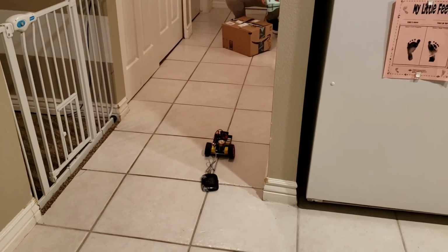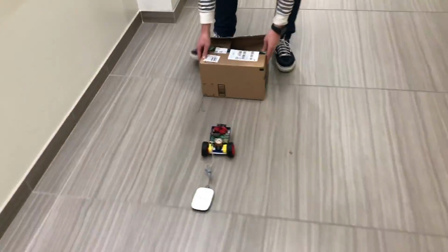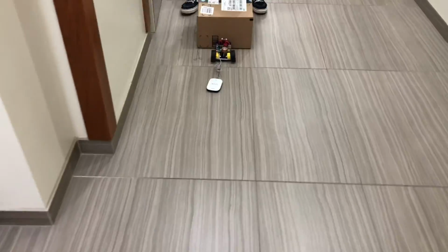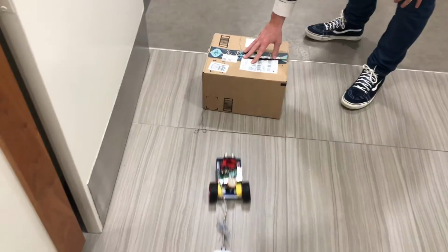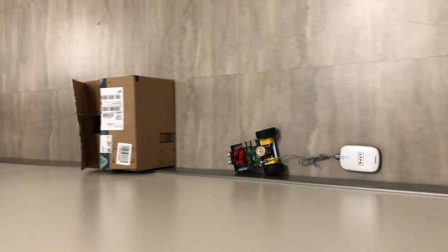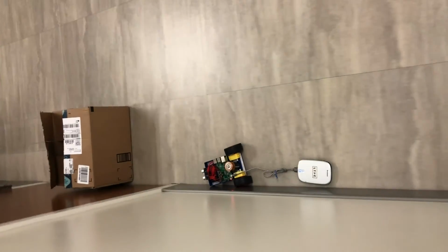Here we have one of our attempts at the doublet test. As you can see, we had some difficulty in controlling the box with the speed of the mixer, which you will see in just a moment. In this other test, you can see my hands in the top right corner. Later on, when we were trying to tune the controller, we had issues with the car not going in a straight line because of drag caused by the battery dragging behind, as well as just imperfections in the chassis and in the wheels themselves. So we decided to try and push it up against the wall, which worked pretty well, but the issue was we ended up running into things like that, as well as, you'll see in a moment,